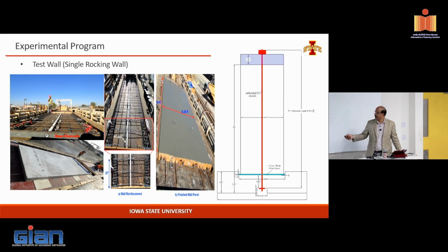They will bring the rebar sticking out, and then they will put a grout pad, drop the next wall, and then they grout it. Because they don't open, they don't crack, it doesn't cause any issue. So that's pretty commonly used. The problem is if you're starting to open, if you're in a critical moment region, like the plastic hinge region, it has become a challenge once you modify it.